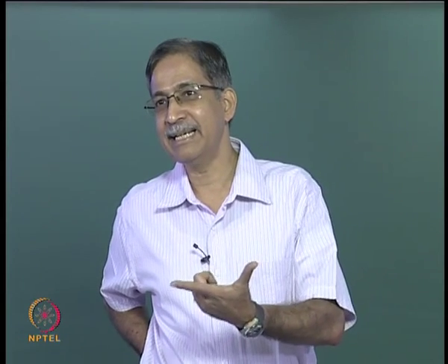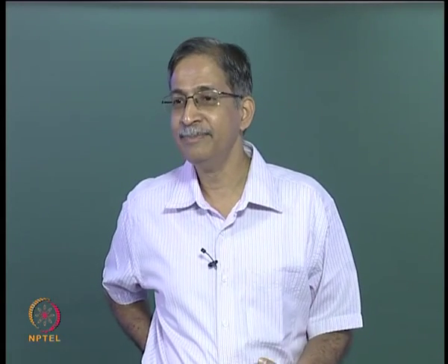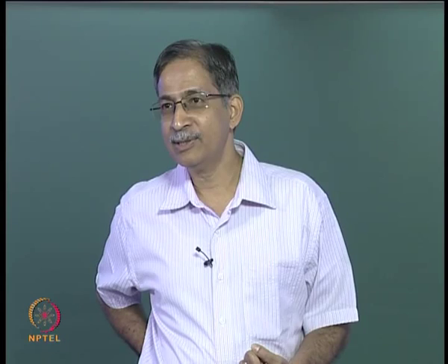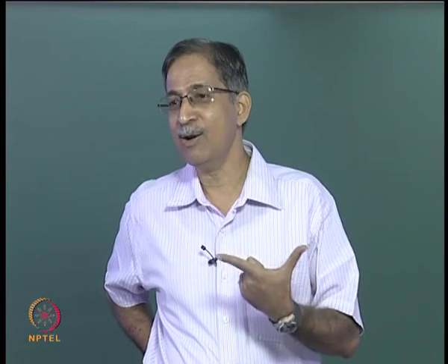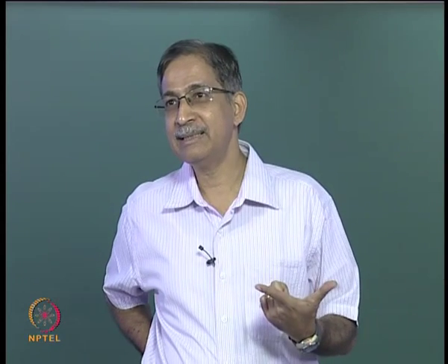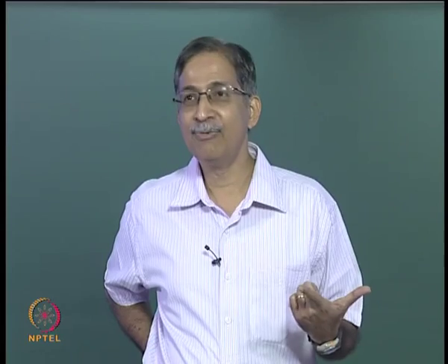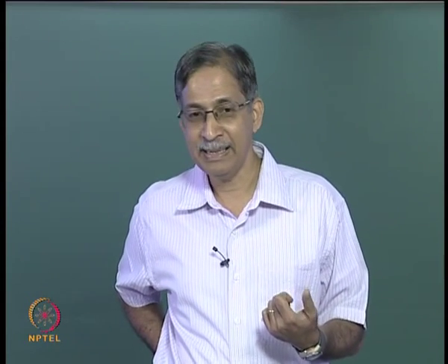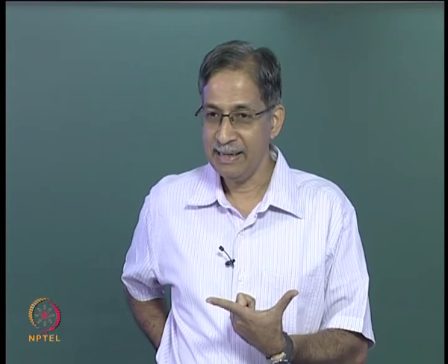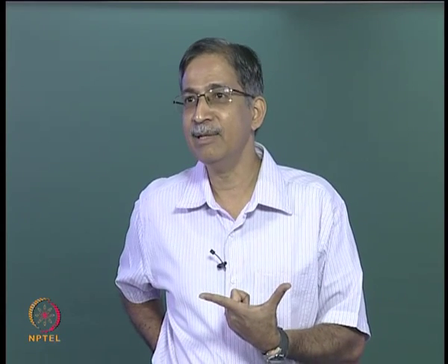So let's just look at element 2. E02, for example, you can do for E01 and 3 as well, but let's just take the second element because it's nicely horizontal. So E02 was 1.32 mm, and if you want to find the final elongation, which you can get from D4 minus D1, because D4 is a horizontal deflection at C, D1 is a horizontal deflection at B, that must be the elongation in the second element BC.